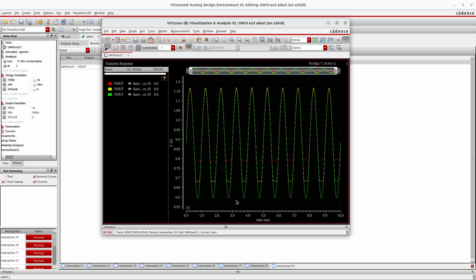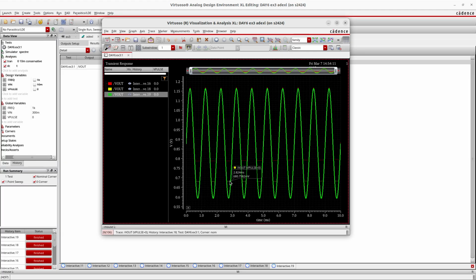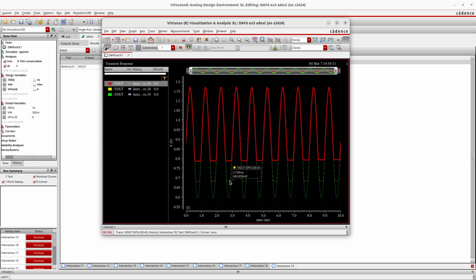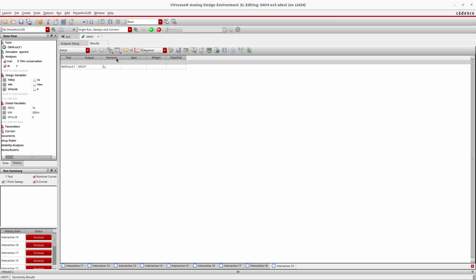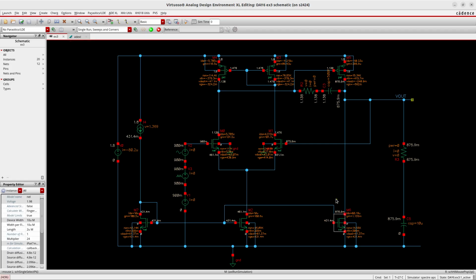Now, in theory, we need 60 microamps, but in practice, we need to take a lot of margin because components will behave differently over corner and Monte Carlo process and voltage variations. So we need to take margins, and that will really change from application to application. Not only will the transistor change the performance, but there will be cases in which you're driving resistors on chip or capacitors on chip, and those have very large variations.